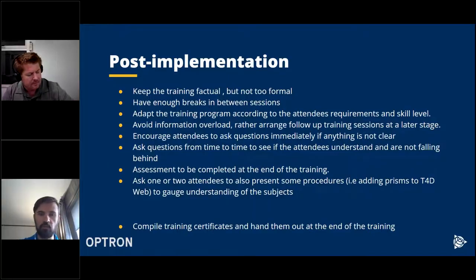Mm-hmm. Another one was about the types of power. You showed some solar panels earlier on. Is that the most common type of power for monitoring, especially I guess total station, but maybe it's different for other sensors? Actually, the most common that we find is to have a permanent electricity supply. It's also the easiest one because we still install backup batteries. So if that electricity supply goes down, the backup battery will continue running. But if there's none, we try to install solar as a last resort.